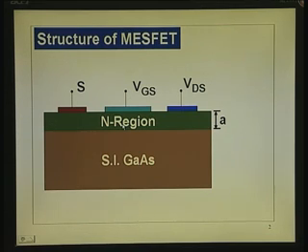So, all that you have now is an insulating layer which does not do anything, it is a mechanical support, a N-type layer with 2 contacts at this point and at this point, from here to there. So, you can say that the current collection begins from this end, current injection from this end. So, this is the source, this is the drain. Usual term as for MOSFET, source is the source of electrons, drain is the drain for electrons. Current flow will be in this direction if I apply voltage between the drain and the source.